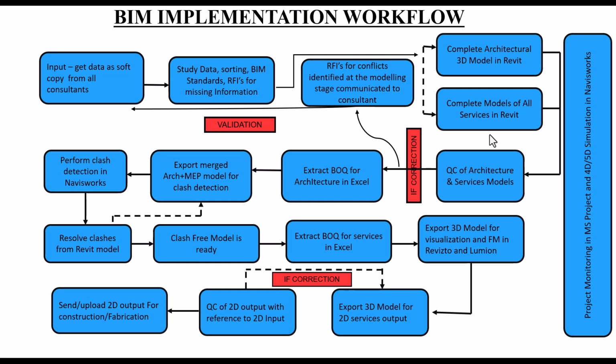Now if we talk about scan to BIM, or BIM to CAD, that is also very much relatable. Whereas in other cases, instead of drawings and documents, you might be getting a point cloud model if you are going for a scan to BIM, right? You study the point cloud, you study the images, you locate the coordinates of where the project is.